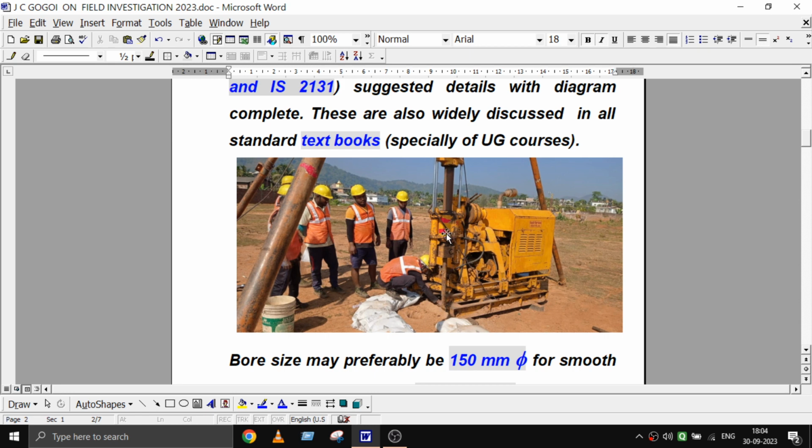Then the sample will be of very good quality, with no extra disturbance, statically penetrated, and at the time of taking out, a gentle 5 to 6 turn rotation shall be made, and then pull it out. If we do not rotate 5 to 6 turns to shear, there may be some damage of the core inside.